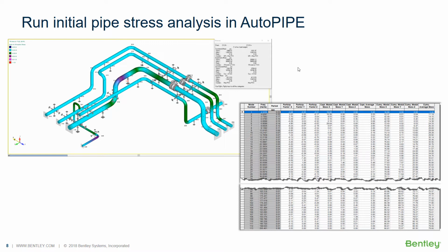So what we see to the right in our frequency report is that we have a natural frequency. My first frequency, mode number 1, is 4.522 hertz. And we're capturing 112 modes. It looks like 113, but I'll show you when we get in there. The 113 is actually not capturing additional mass participation.